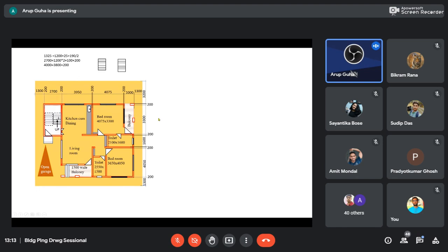At the sill level we have put a horizontal cut, so that is actually 900 millimeters above the floor level, 1500 millimeters above the ground level, 600 reaching the plinth, another 900 reaching the sill level. There we have made a horizontal cut, and then we are looking from somewhere from the sun. That will give me a plan, because everything we should be seeing in parallel vision. Parallel vision means not seeing through one pinhole.